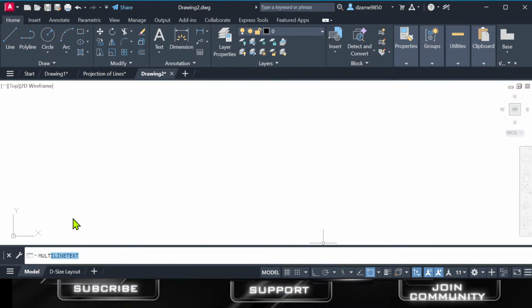You may not be able to see, but it says a multi-line or whatever it is. You type L as line and press enter, and it says specify the first point. I can just pick anywhere in the work area. I click there, and it shows I'm drawing a line. You can draw and close, and that's it. Basically that's how the command line works, or you can go straight here and pick the tool that you want and just draw. I'm just running quickly so at least we understand what we want to work on.